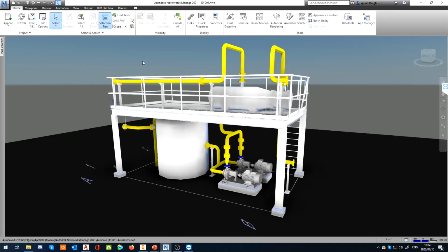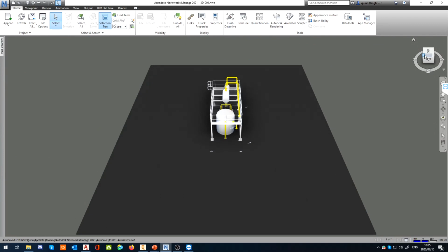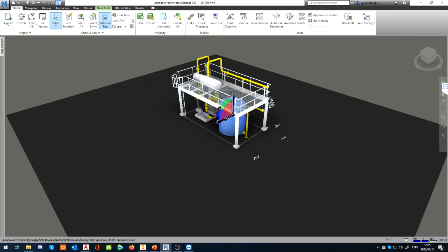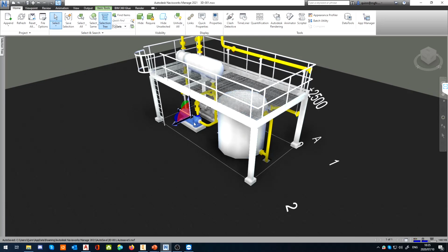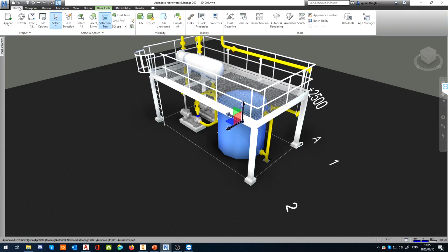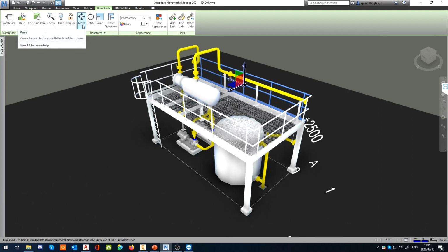Going back here. One of the things that you may have noticed is that when you are moving things around, or when you've selected something and you're using a different tool, like maybe move, rotate, or anything else, if you hit escape or do whatever you want to do, you notice that I've still got whatever I had selected last, especially move and rotate, which are some of the worst ones I've found. You still have that selected as your selection system. You notice it still wants to move things around. I can't just click on it and try to do something with it. It's a little bit difficult to explain, but basically it's because it remembers that my item tool is currently set as the move transform. We don't have it set as the selection item.